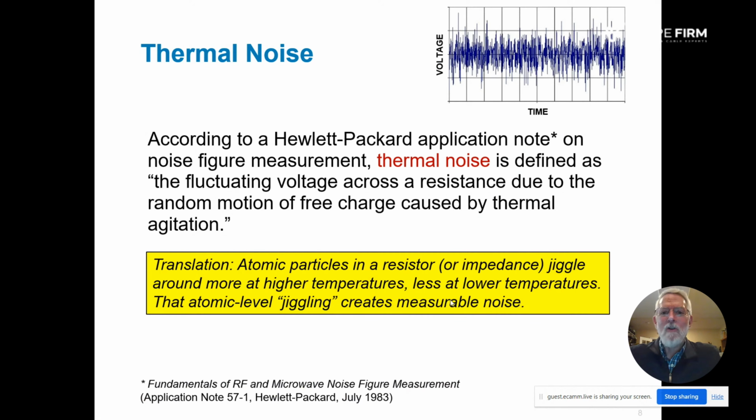And Brady, back to your question, how on earth can a resistor sitting on the table at room temperature generate thermal noise? It involves a little bit of physics, and it involves kinetic energy and ionized particles, so think electrons and ions, when connected via a suitable conduction path, such as the metallic leads on a resistor, can convert that vibration to a measurable thermal noise.